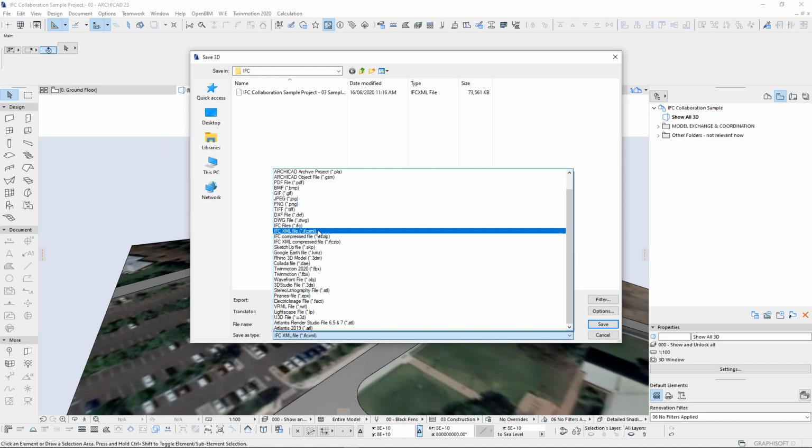The difference between these two resides mainly in the capacity of either format to describe not only the building elements, but their relationships. In general, IFC is a plain schema based on something called EXPRESS, and that type of format is expressly defined for building information. XML is an open format that, although far more widely adopted, is not capable of describing certain relationships between the building elements.